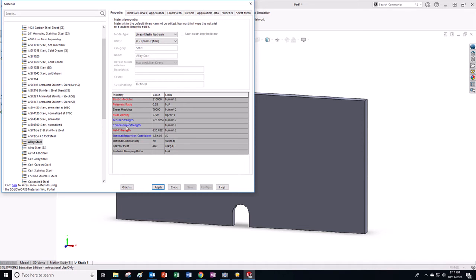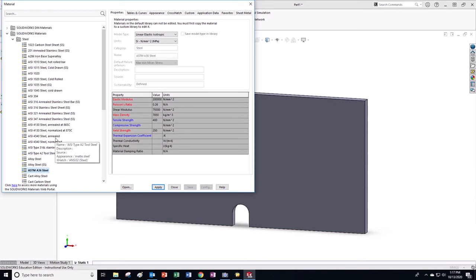But you can take a look at the yield strength of this, it's 620 in that alloy, and if you wanted to come down, and of course they changed things on me. What is that? Oh yeah, okay. So that's megapascals. You see the yield strength is 351. If you go to A36, where's A36? It's right here. You can see that this one has a yield strength of 250, right? So we're actually something smaller than that. Maybe a low carbon steel, they go 180 right there for hot rolled and cold drawn.